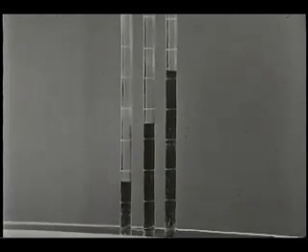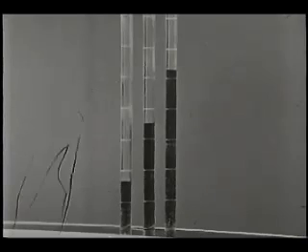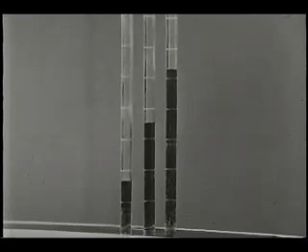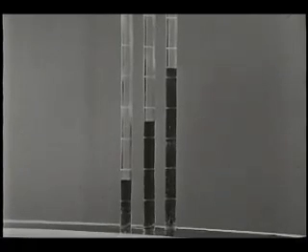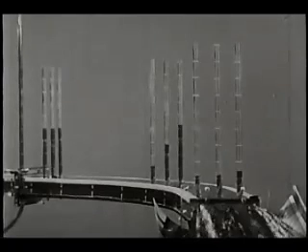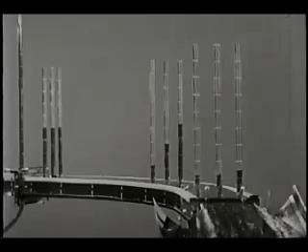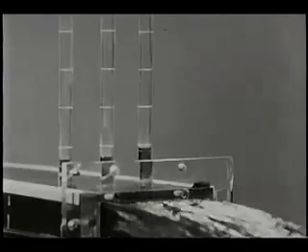This is close to what we would predict using Euler's equation for the normal pressure gradient. Downstream of the bend, the pressure is almost uniform again. The slight variation there is due to a complicated secondary flow induced by the bend.